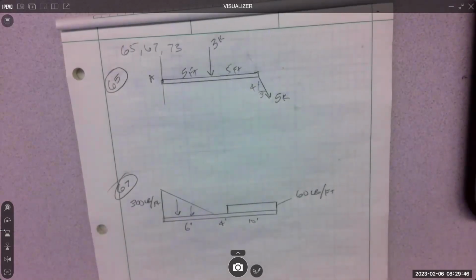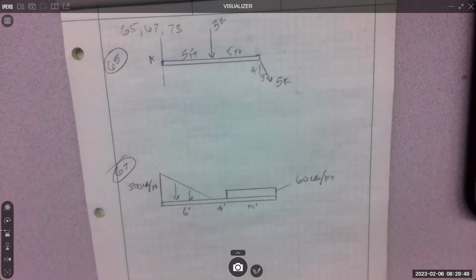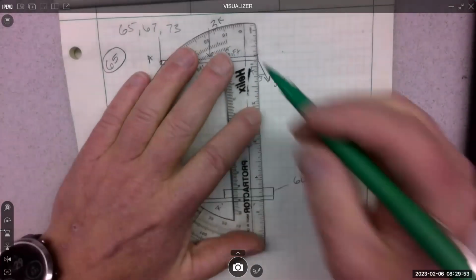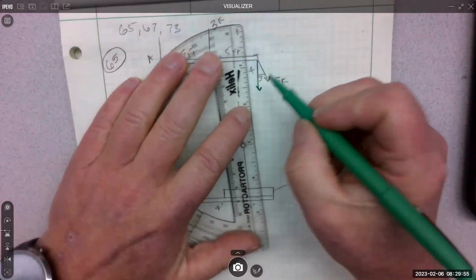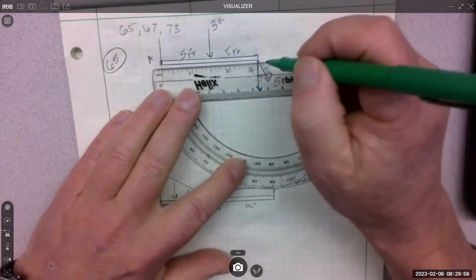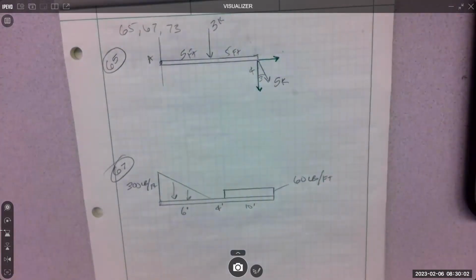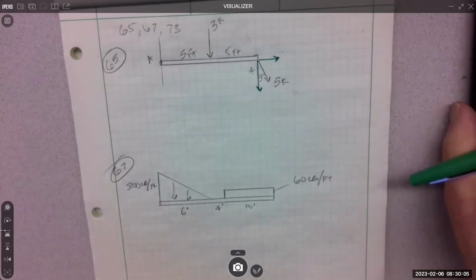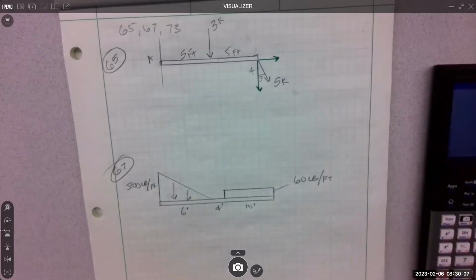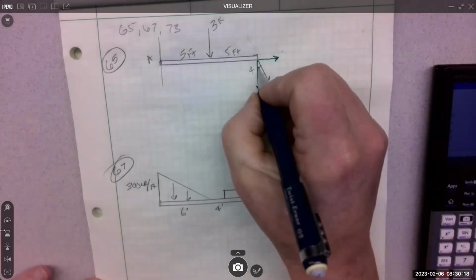What do I do first when I see forces at an angle? Get the X and Y of it. Turn it into its components. I know there's down effect and I know there is to the right effect. Yeah. So I would find the angle 4-3. So I'd go 3/4 and inverse tangent to give me that upper angle, 36.869. That's this thing.